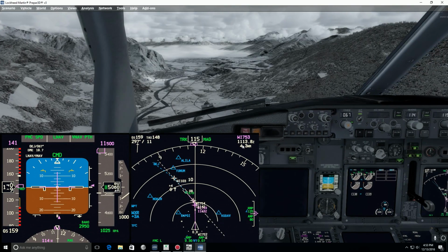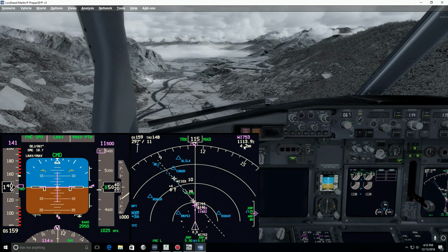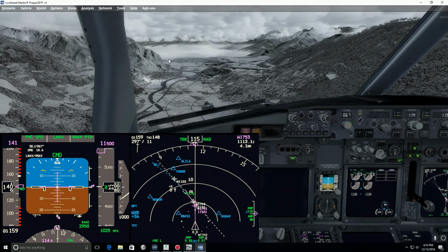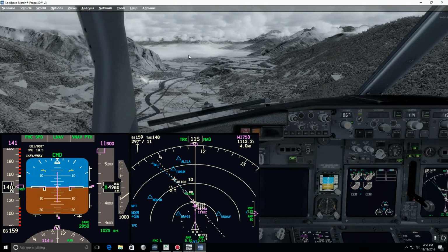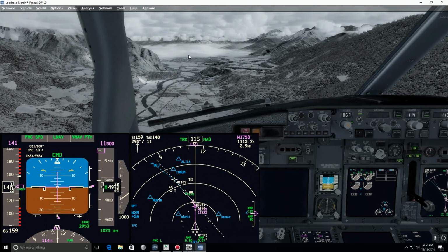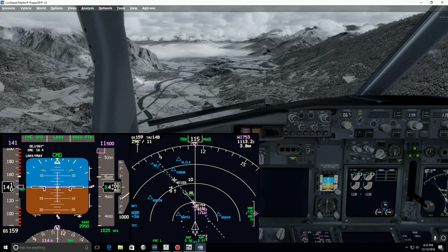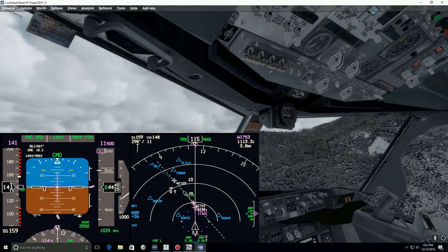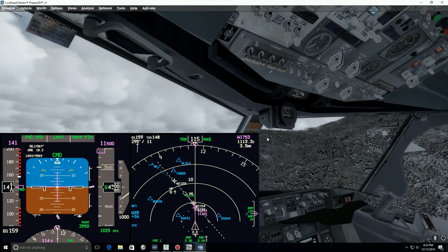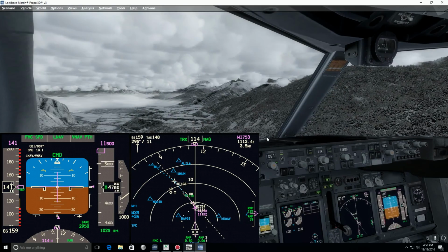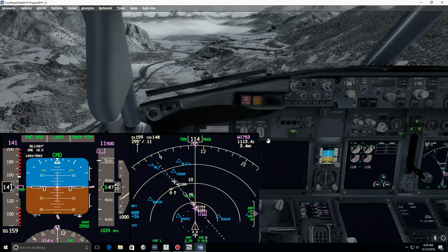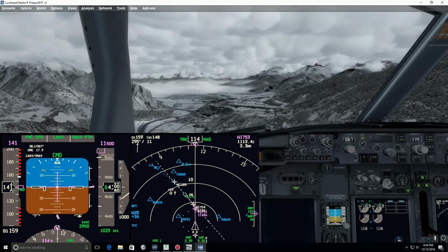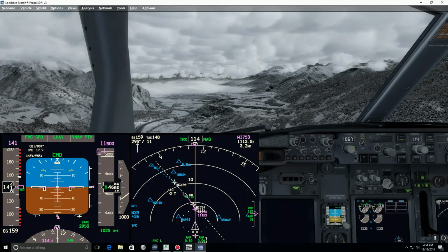We will do the left turn in 4 miles. We will turn toward the runway. I see in front of us a little bit of clouds here. That's the few cloud at 500 feet. It might be a problem. Let's hope we see the runway. Okay, just been cleared to land. Taxi light on. So now we're all set, ready to fly this approach.